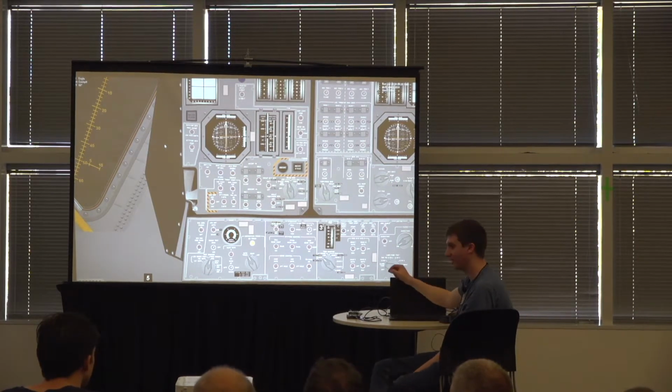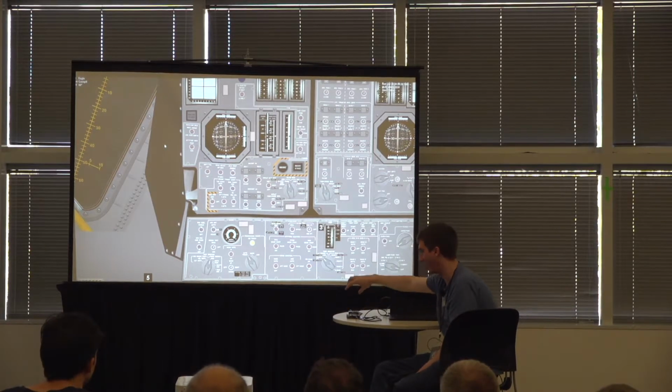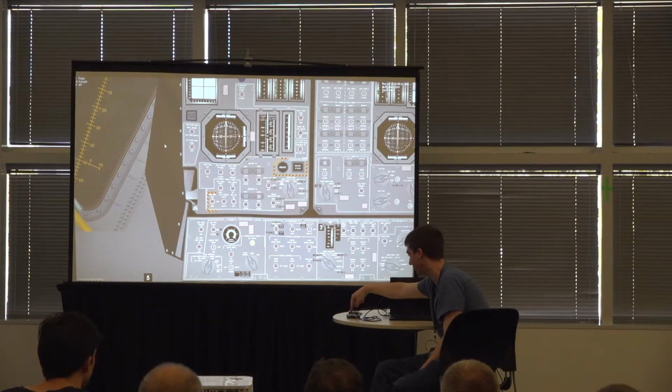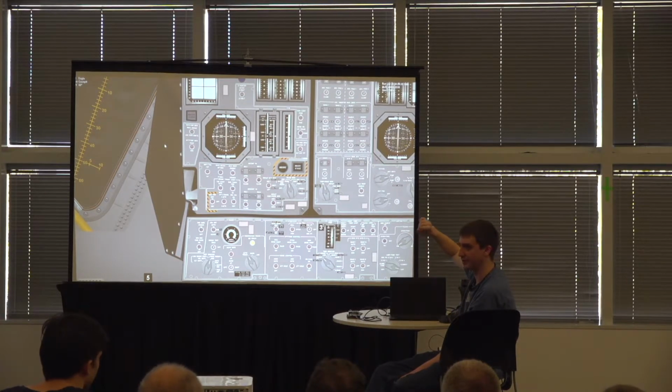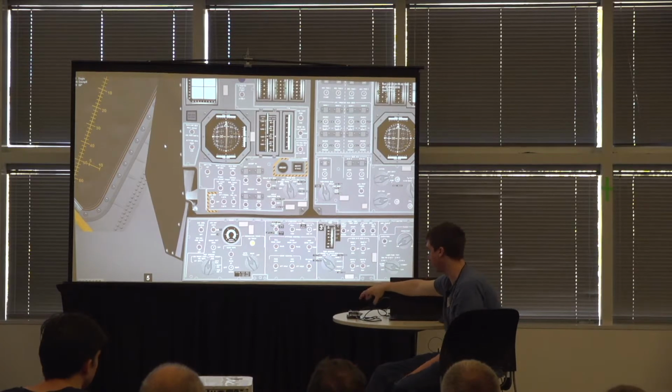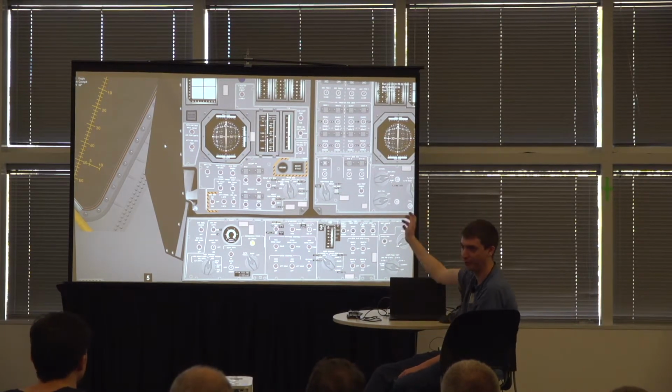Yes. So the way that I'm doing that is my debugger has the clock from the AGC going to it on the AGC's test connector. So I'm able to count clock cycles. And I also have an input to halt the AGC. So I have a little Verilog core in the debugger that counts clock cycles and periodically halts execution of the computer to more or less match the load that they were getting on Apollo 11. So those were real 1202s that we were seeing.